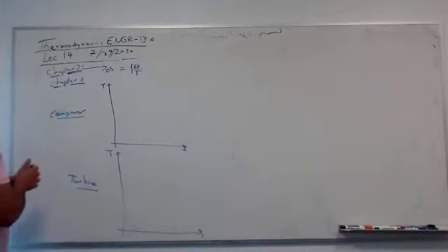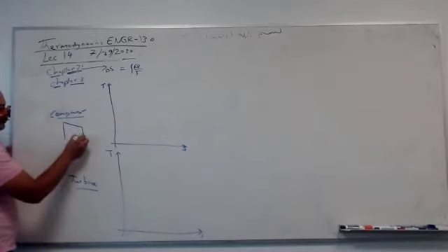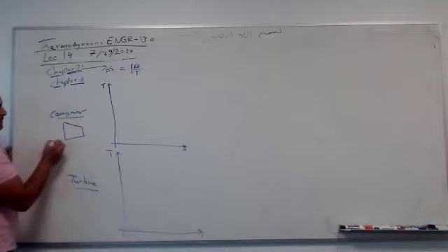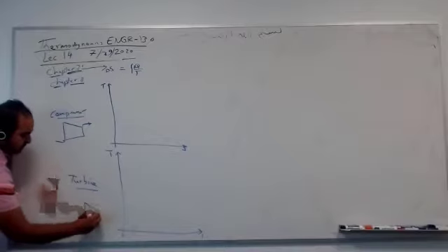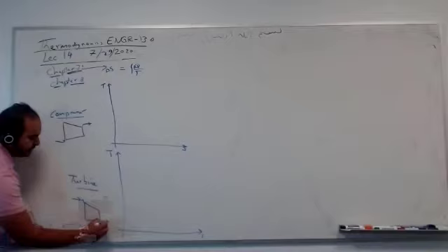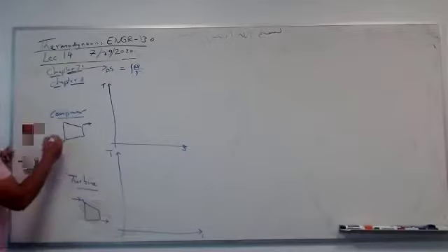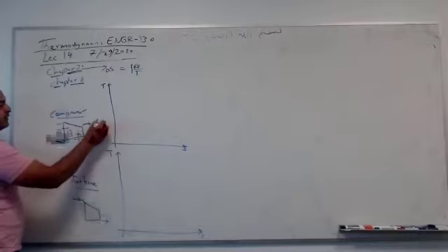A compressor is a component in the system where we compress the flow coming in with low energy, going out with high energy, and higher pressure. A turbine is the opposite. It's flow coming in with high energy, going out with very low energy, but we get work. So here I pay work, but I get high pressure, P2 greater than P1.